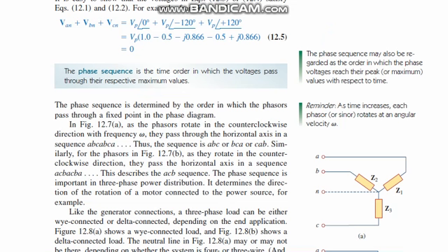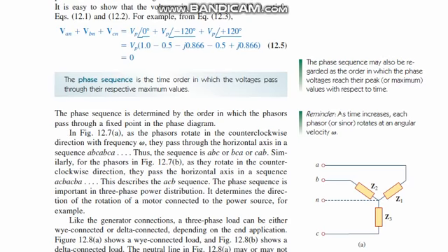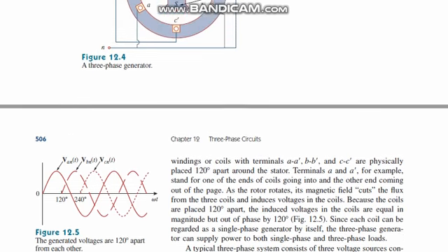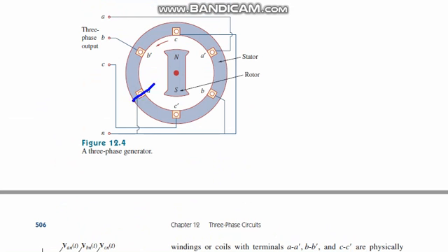It is pretty simple, because when we see the phasor of this, the phases are 120 degrees and 240 degrees apart from each other. Why does that happen? Because as it is three phase, there are three terminals, the A terminal, the B terminal, and the C terminal, and each is 120 degrees apart from each other. So while this magnet passes from the A side to the C side, it will take 120 degrees later to respond, and another current and another voltage will pass through.